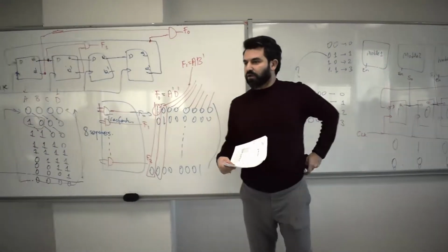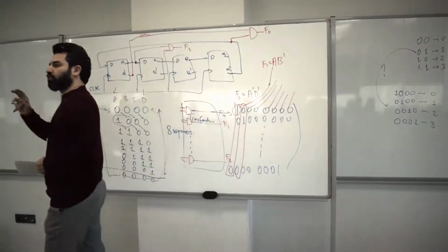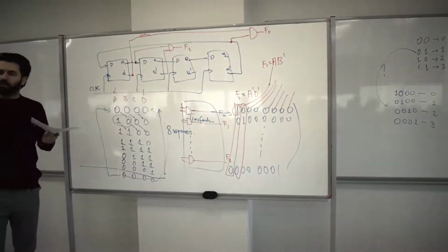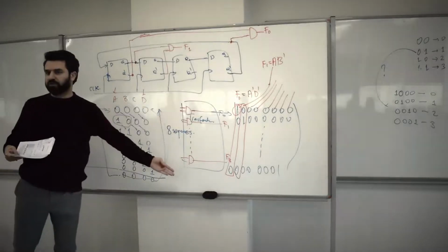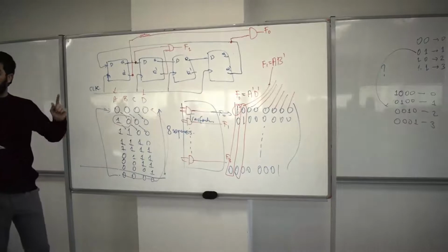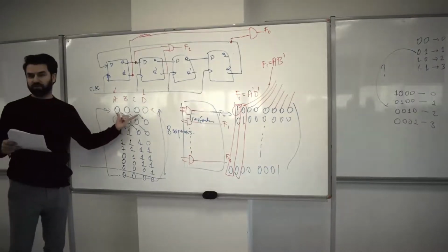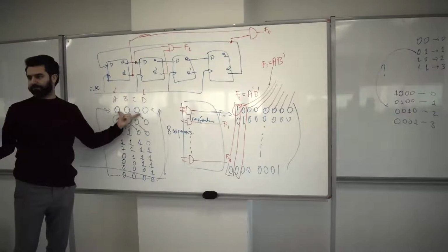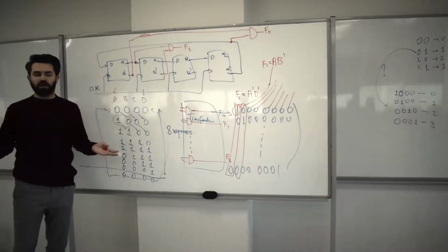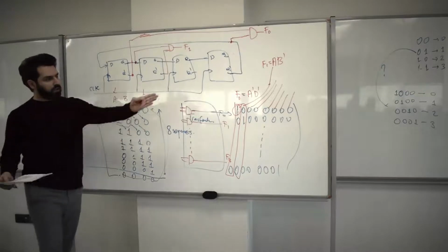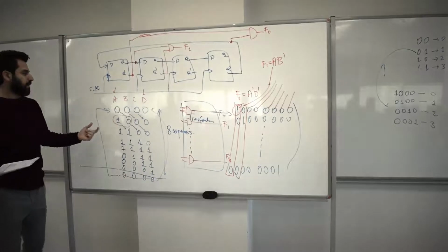So you see, the Johnson counter solves two problems, almost perfectly, let's say, but not perfectly, of course, because now you're using combinational circuits. But almost perfectly. The first one was the initialization problem. So now you can initialize from 0, 0, 0, 0. Which is good, okay? You may not have sufficient equipment to initialize the ring counter to 1, 0, 0, 0, okay? So this is good.